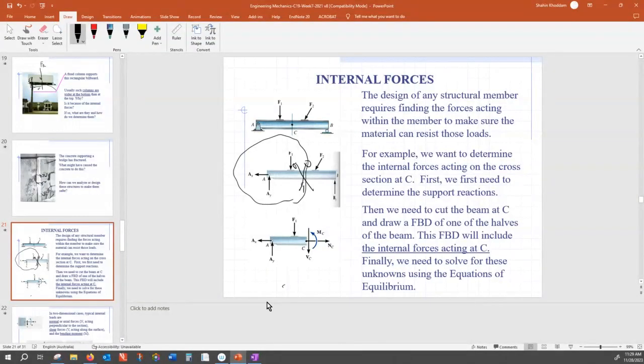Okay, so as a recipe, memorize what I'm telling you. In every beam, there are three internal forces developing. The first one is axial force, and the symbol we use to show that is N. The second internal force is shear force. The symbol we use is V. The third internal force is bending moment, responsible for change of radius of curvature. We use the symbol M.